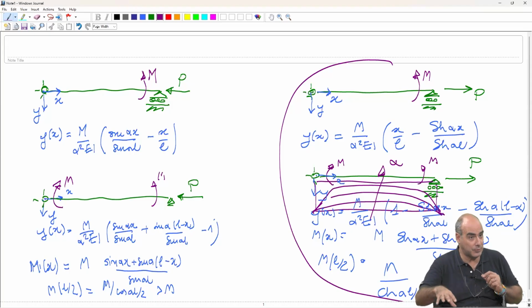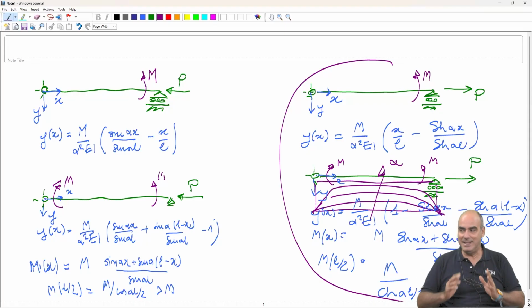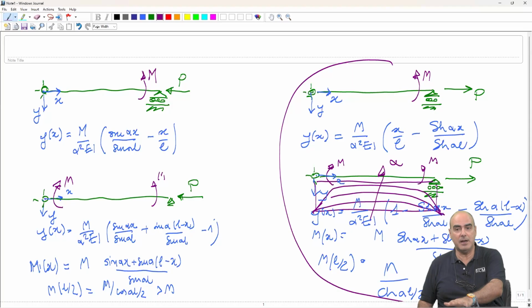So there are structural applications. Don't think only of beams and columns because you say, okay, but when do I have a column under tension? Well, you can have it if you have a very strong earthquake action which activates this, but it has to be very, very strong. But you can have structures which are purposely designed to work under tension because they do not resist otherwise.